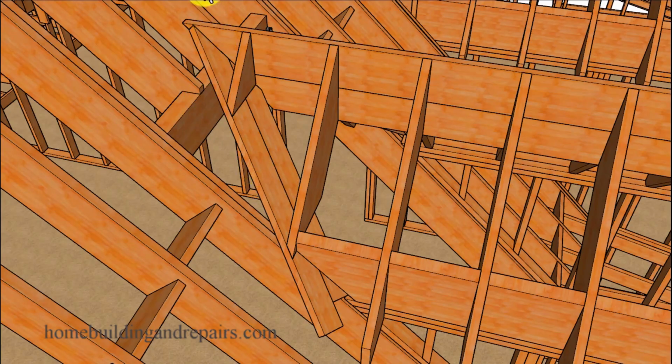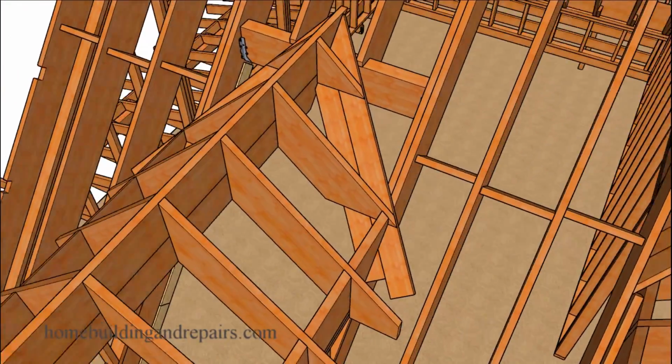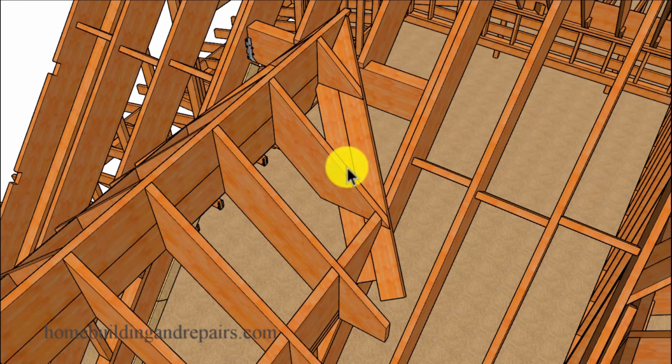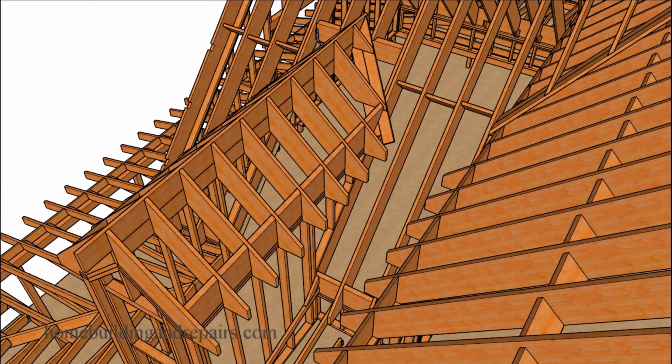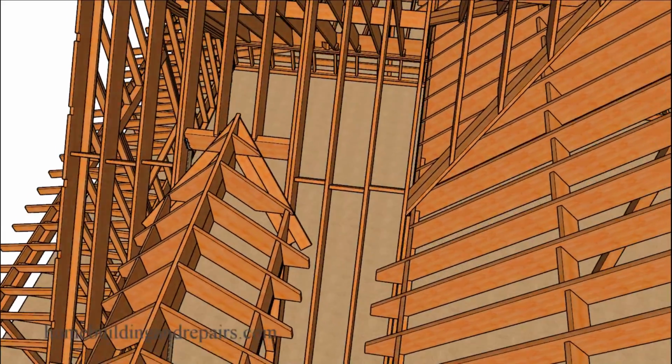I didn't because I wanted to show you something I've done before, and that would be to build this dormer roof over this roof. I'm going to install my sheathing here and then nail the roof sheathing to the bottom of these boards here. I've done that before and nobody's ever had a problem with it. However, if that's not going to work for you, don't do it, of course.